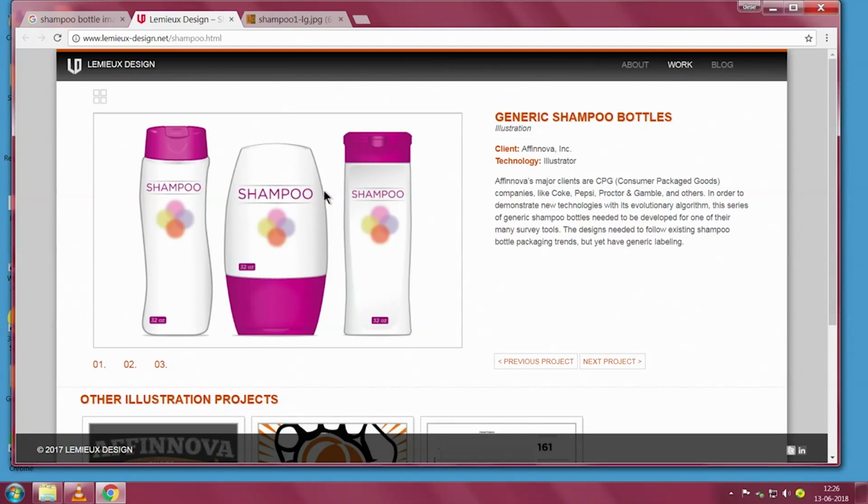These and children's toys and several of the other things are all made with blow molding, meaning usually a small former is prepared and that is put in a mold, and then after that air is used for expanding and it fills the shape available.